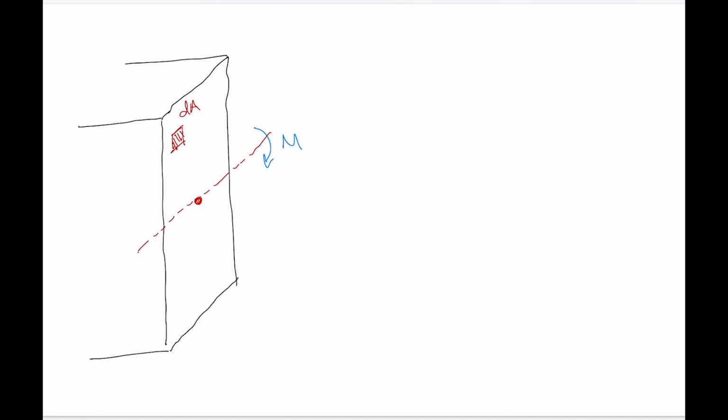And we know, being above the neutral axis of bending for a moment in that direction, it is going to be experiencing a tensile normal stress. So here's normal stress sigma, and the location of that piece of material relative to the neutral axis of bending, the centroidal axis, the axis that M is acting about, is given by distance y.